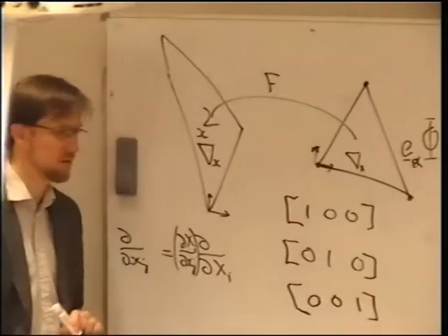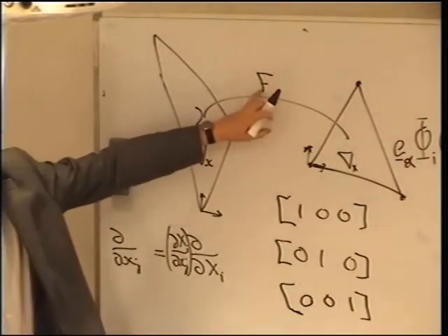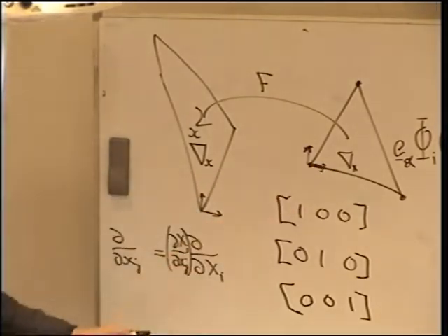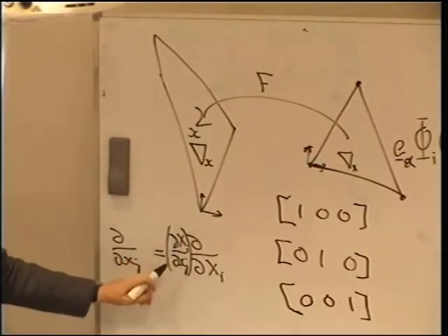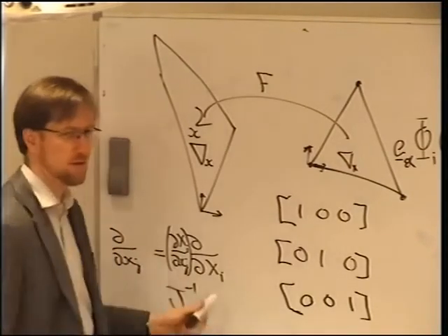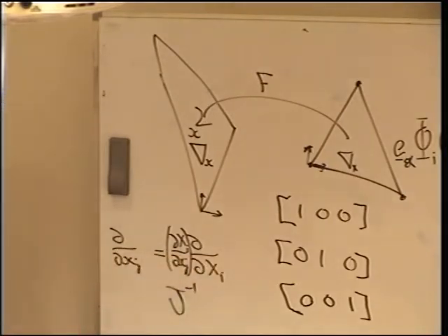And we call that the inverse Jacobian. So the Jacobian would be d little x d big X, right? That's the gradient of this function. So this function gives you small x's given big X's. So its Jacobian will be the other way up. And so this we call J inverse. And so you have to transform the gradient with this to get from here to here.